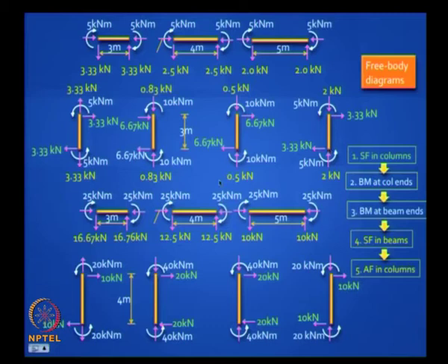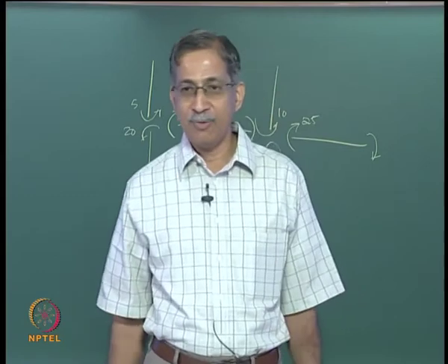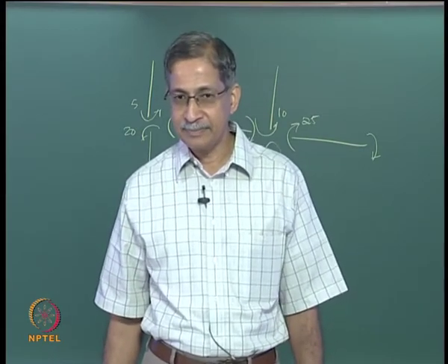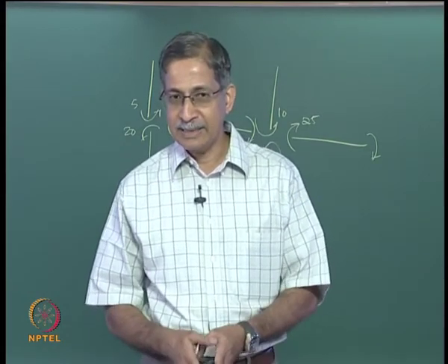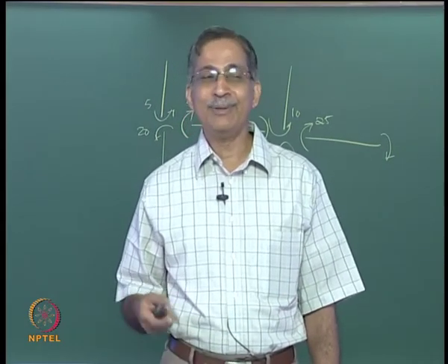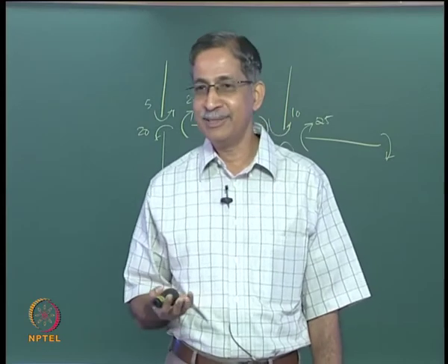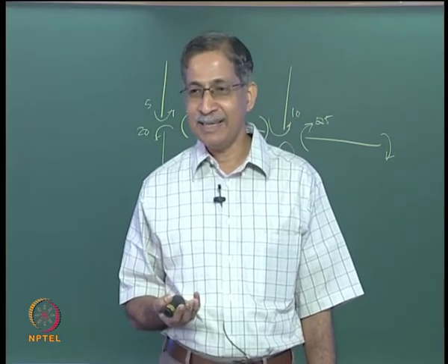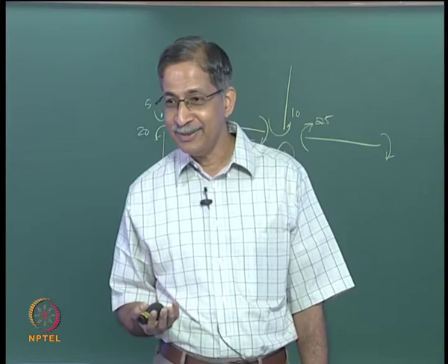Clear? Now you come below. You want to get this, you can work it out. Okay, I'm not giving you all the answers, you can easily work it out. What's the next? So you got the column axial forces. What's the next step? Have you got everything? You can also find beam axial forces. How do you get that? Do you get it from column axial forces?